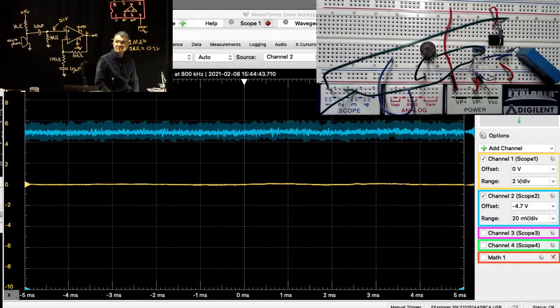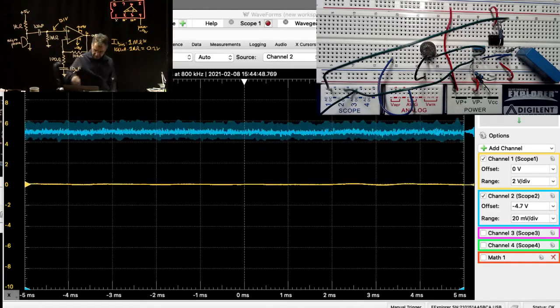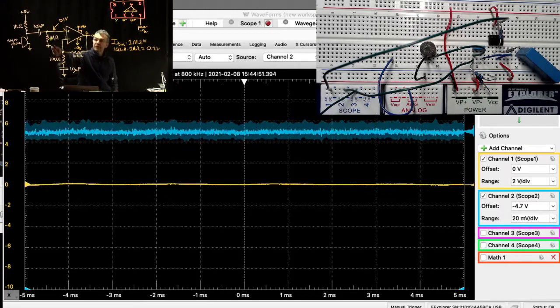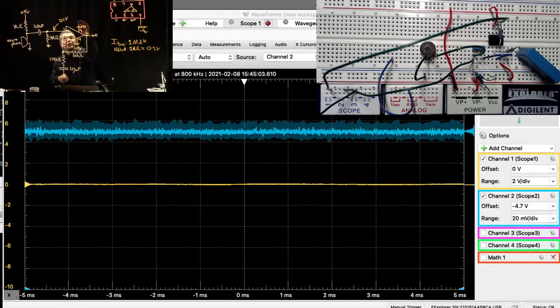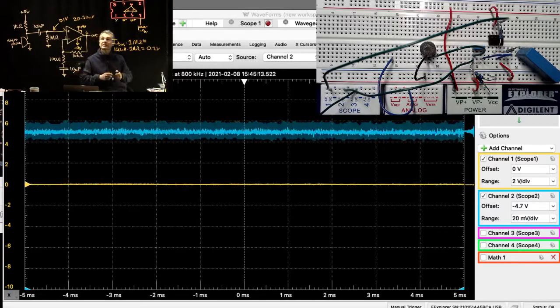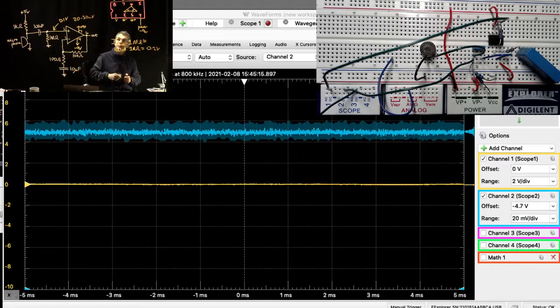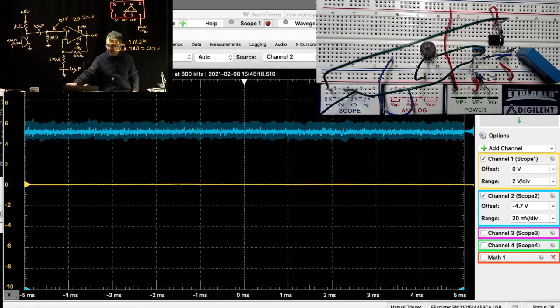And the reason is that I bias flows into the op-amp through this 1 mega ohm resistor, so then there's an IR offset of, well, I was thinking it'd be a tenth of a volt. It just seems like from observation that it was more like 20 or 30 millivolts instead. So it's kind of like a factor of 4 smaller than I expected.